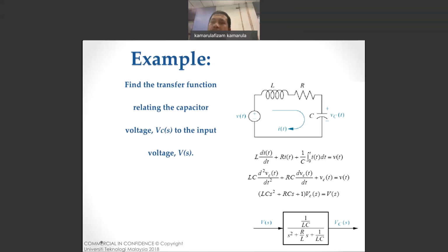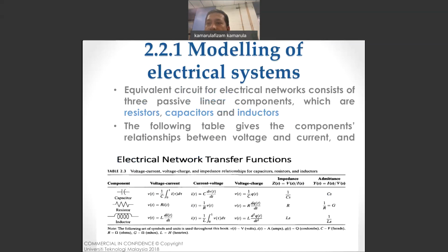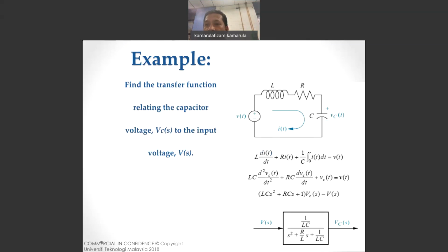So you can first rearrange the formula. We are working with voltage on the left hand side, equal to the supply voltage, equal to the voltage dropped in each of the components or elements. On the other side, you have to know that V is equal to IR, where R is your impedance and I is the current. Impedance for each of these elements is given here: 1 over Cs, R, and Ls. So you have the 1 over C term, the R term, and the L term. Then you have the current term.